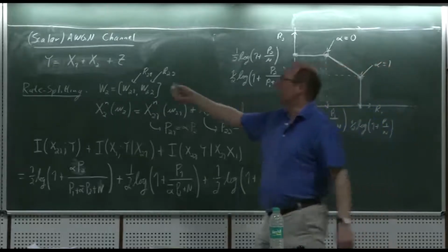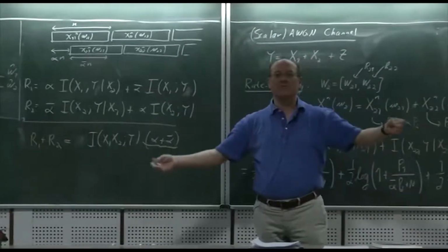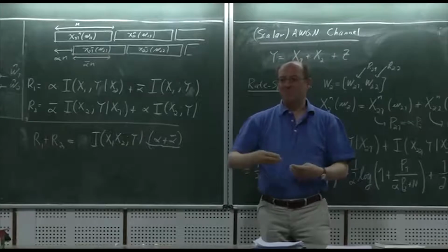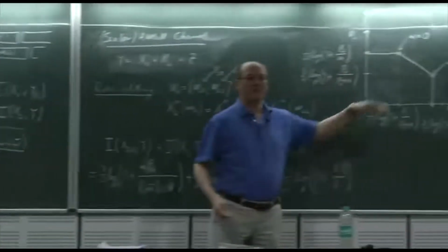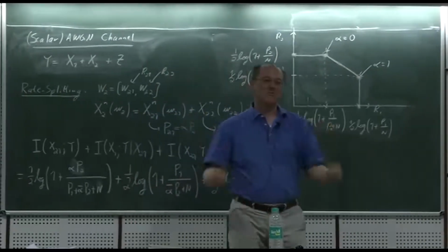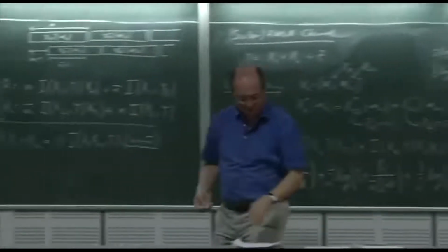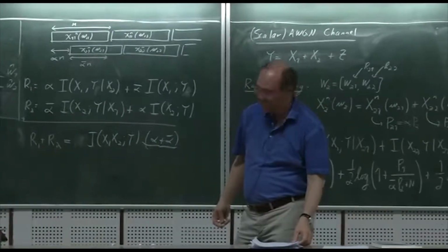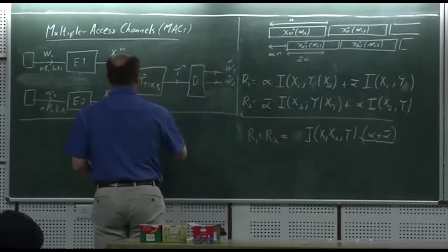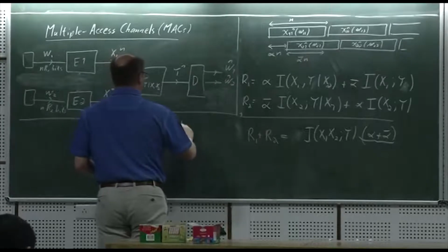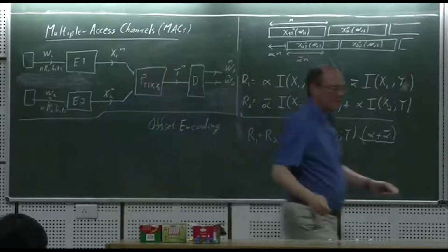And actually, this idea you can apply generally whenever you have multiple users transmitting in a system. It's really just a matter of placing their timing in a certain way in order to move rates around. So it's rate adaptation by timing adjustment. Very, very simple. So I think that's a very nice approach. So that's the third method. I like to call it offset encoding. But I think there are other names for it too, but it's a nice trick.